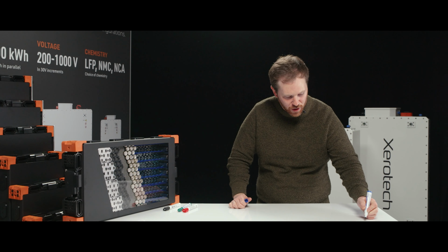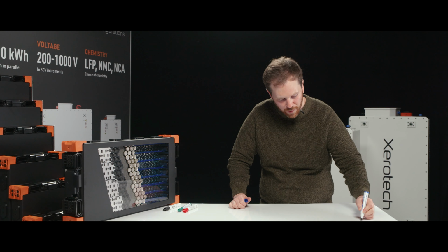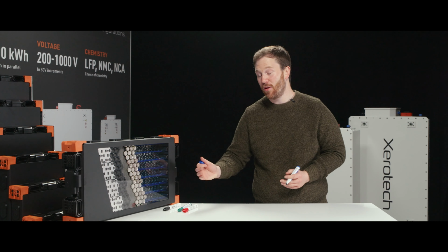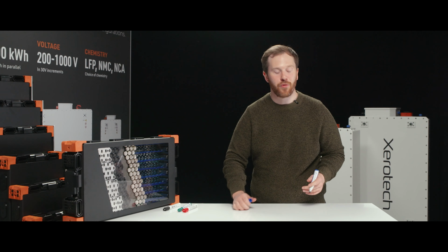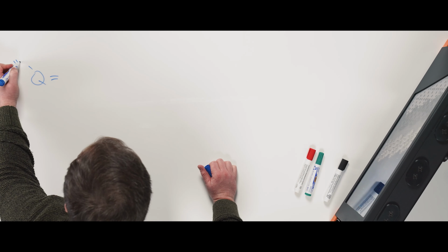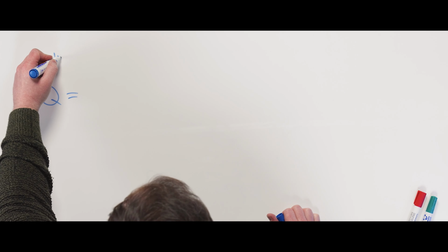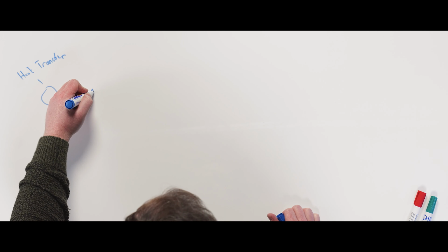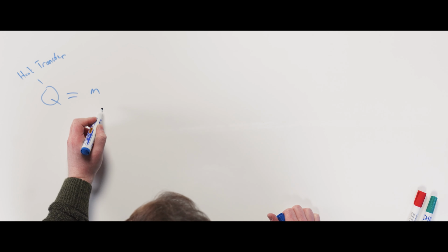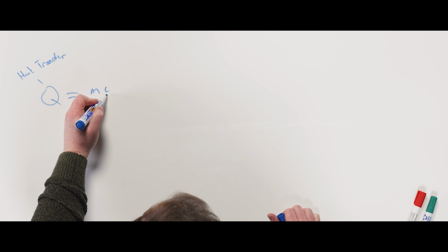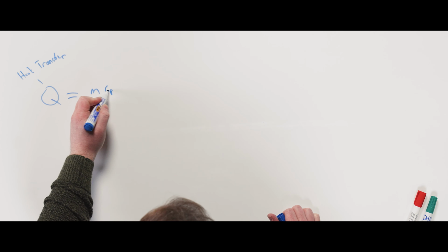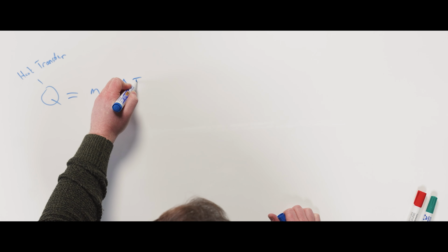One of the most important equations that governs battery pack design, or certainly the Xerotech battery pack design, is heat transfer. There's a very important equation where the heat transfer is influenced by a number of main factors: the mass flow rate times the heat capacity times the temperature difference.